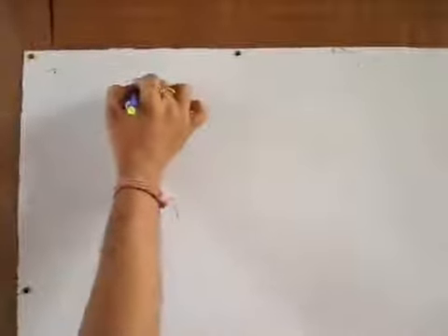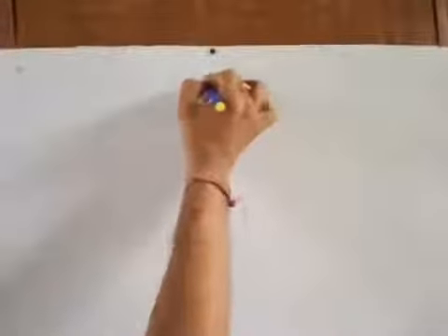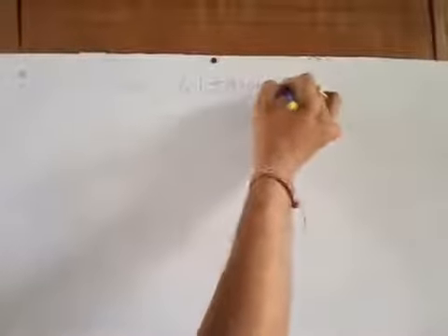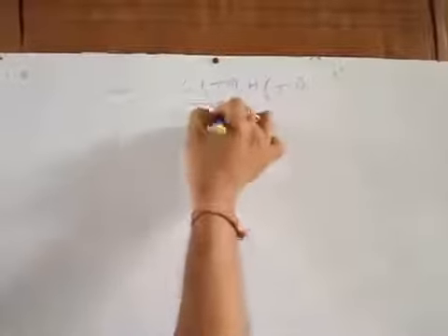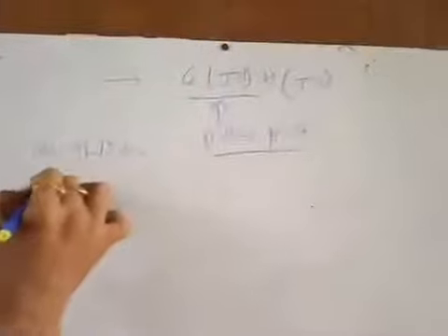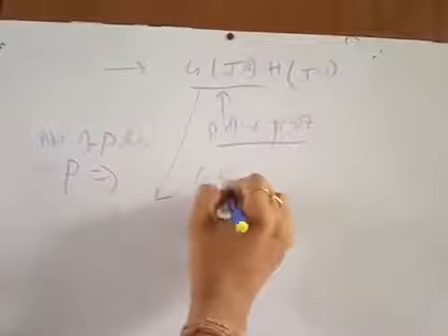First of all, the Nyquist criterion requires the frequency response of G(s)H(s), which is obtained with the help of G(jω)H(jω). That means you can get it by using the polar plot. And the number of poles, P, can also be obtained from this G(s)H(s).